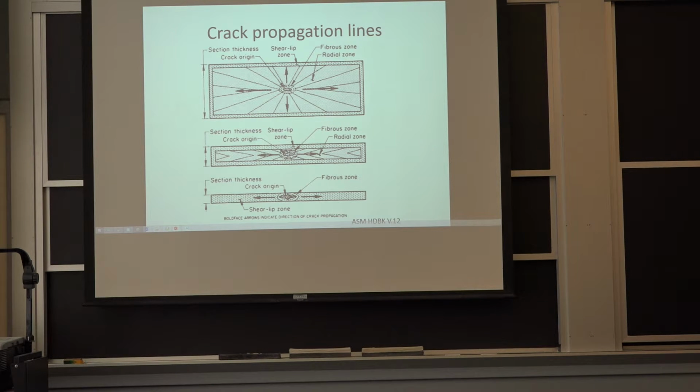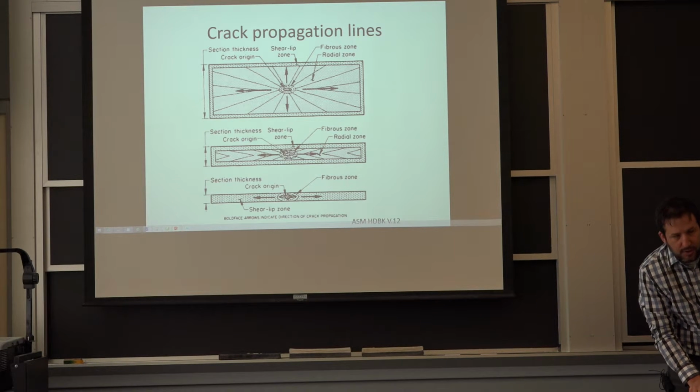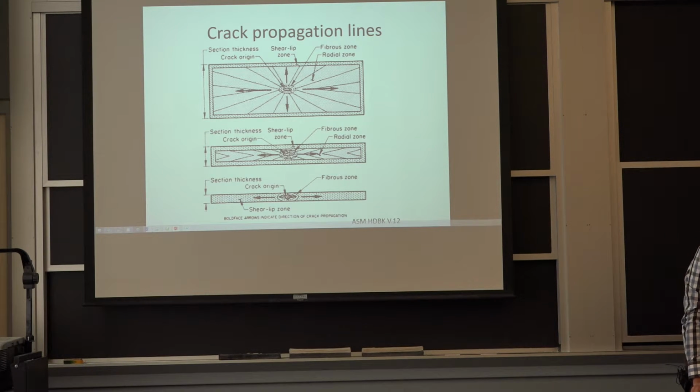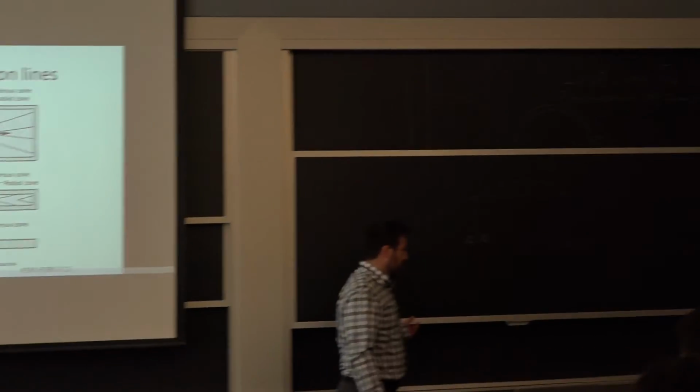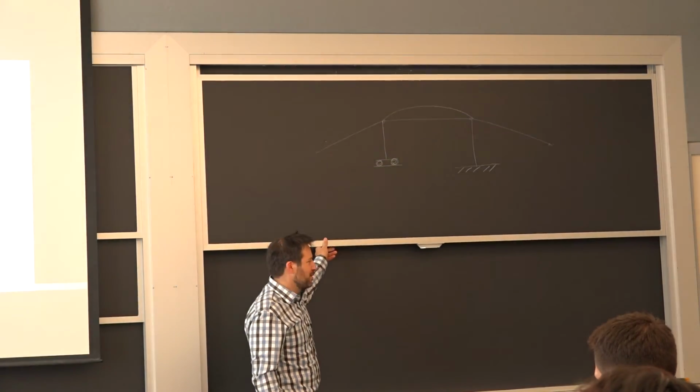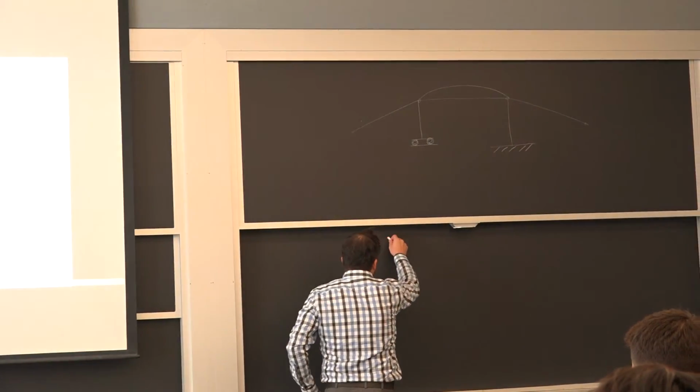Okay, yes, it's a good question. About the crack propagation resistance of material, there's no magic solution. In general, when you increase your yield strength, you do increase your resistance to crack initiation. And the reason is, and that's a slightly different topic, we're talking about fatigue, but it's perfectly fine.